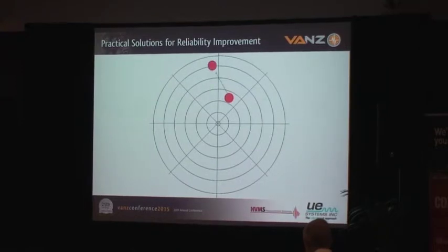On the first event, the imbalance vector moved, not too much in terms of the angular position, but the amplitude doubled. The second actual event was significantly more than the first, as we can see when we look at it on a polar plot, considering the phase and everything.